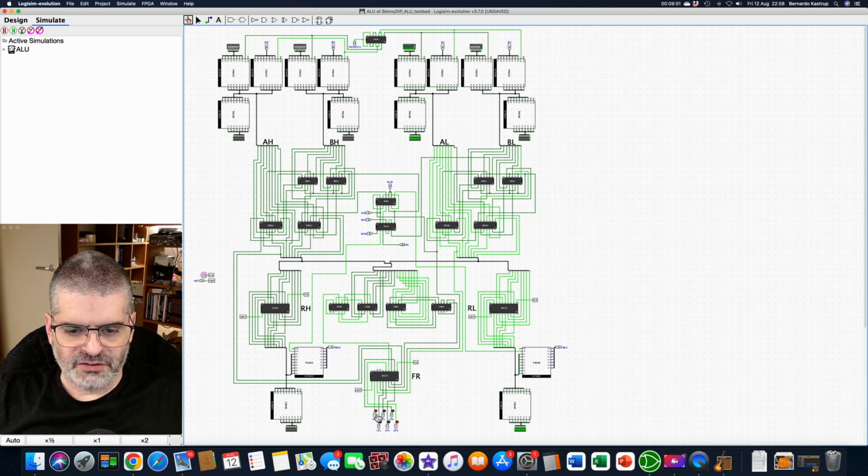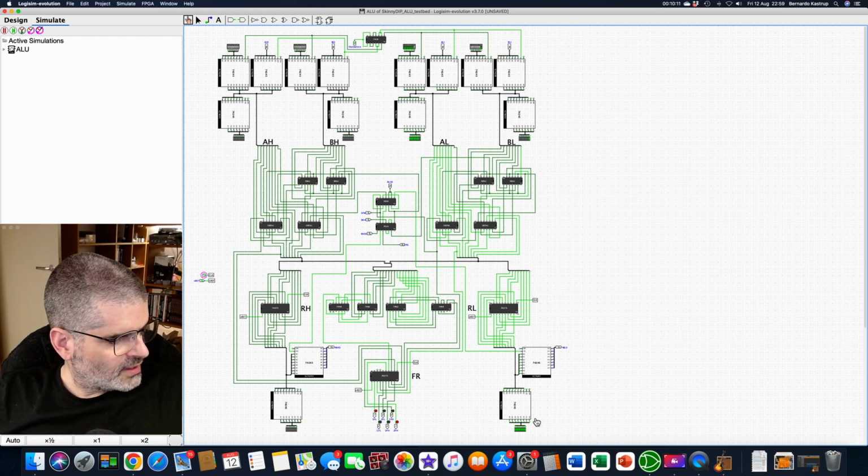The sign flag is irrelevant in this case. It's also giving me a 0 flag high for the upper byte, which is okay because everything is indeed 0 there. So the 0 flag logic is working. And we don't have a carry flag here because this is the maximum number that still does fit in 1 byte. So that's okay as well.